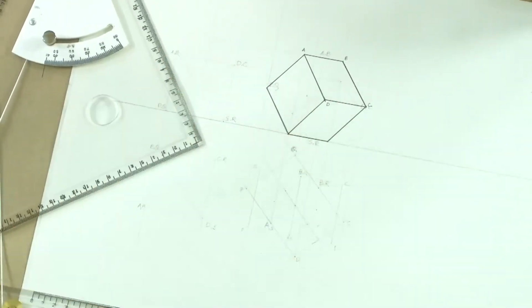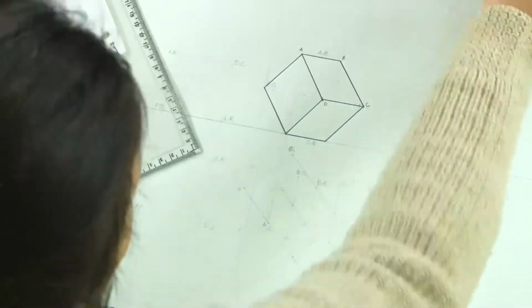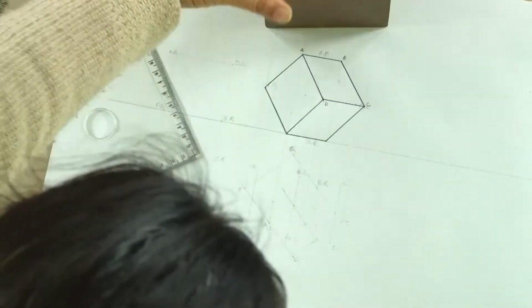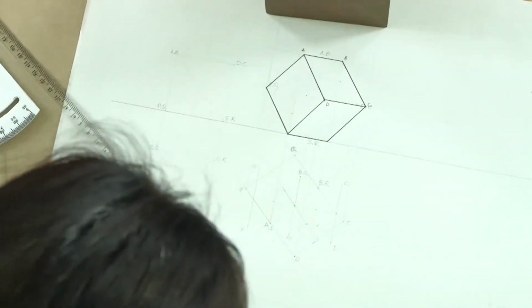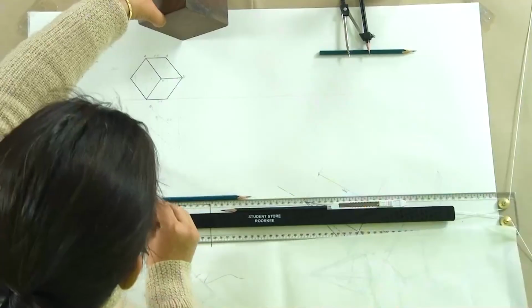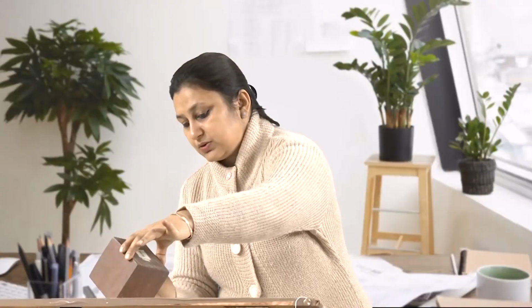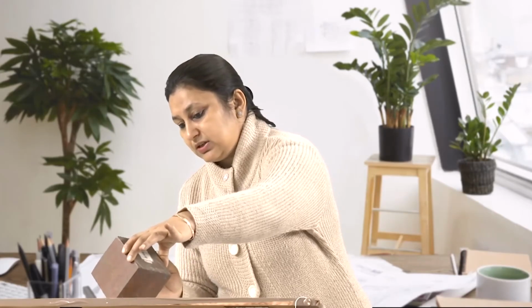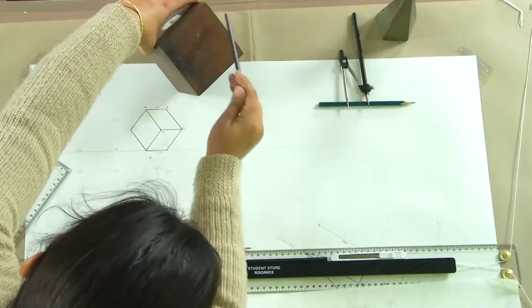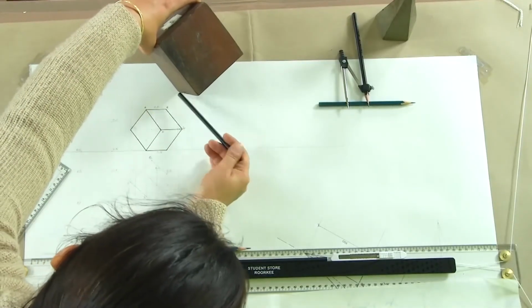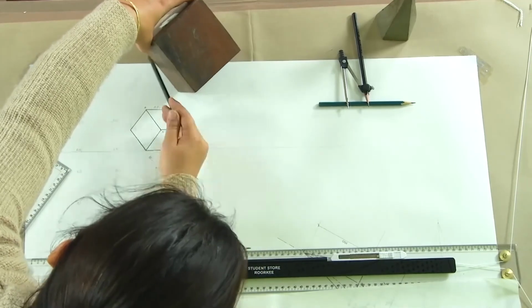Which is precisely what we should have been seeing. With simple logic, this was the cube which was kept originally like this, A, B, C, D, P, Q, R, S, and then we inclined it like this. What we saw from the top were A, B, C, D and P and Q. Now when we inclined it further 30 degrees, we are seeing these three faces from the front. So we are seeing A, B, C, D and P and R and P, S and R here.